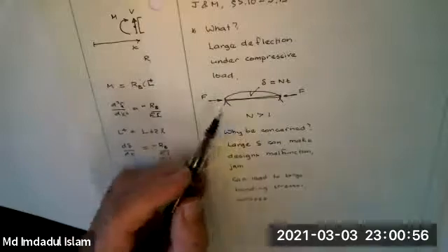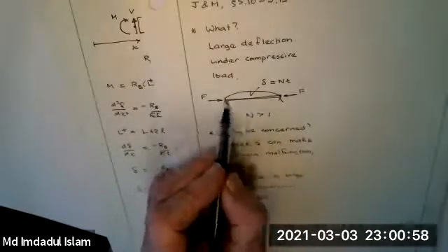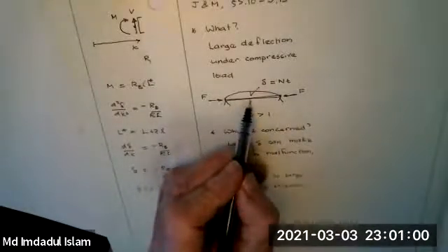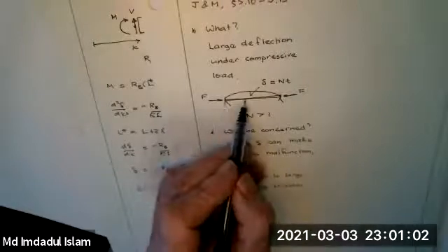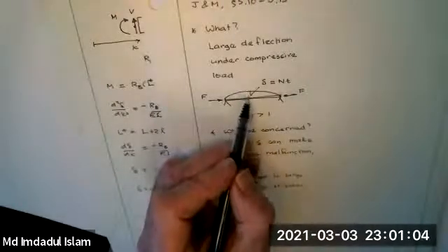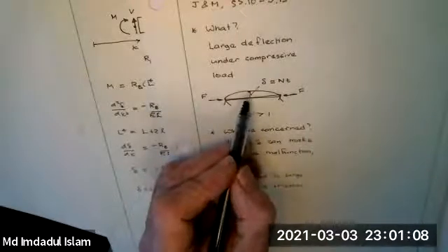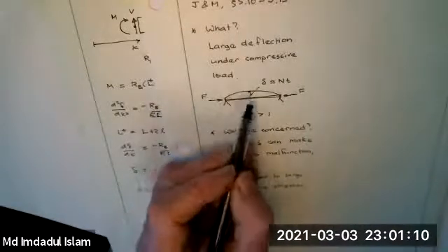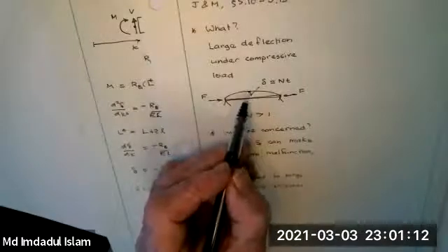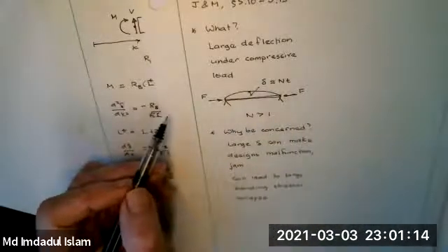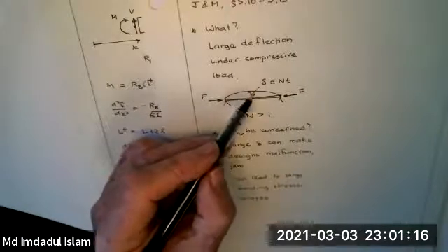Once these things start moving here, in this case here, you just have an axial stress. The axial compressive stress is the force divided by the area. Here you start to get a bending moment when you're out here, maximum bending moment, F times delta, and then you divide by the section modulus. And if this thing is thin, that section modulus can increase that number significantly, and you get a large stress.